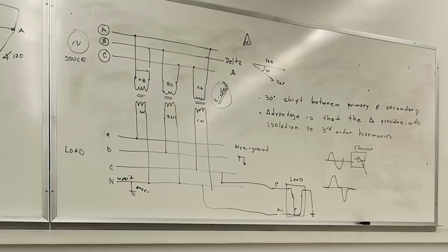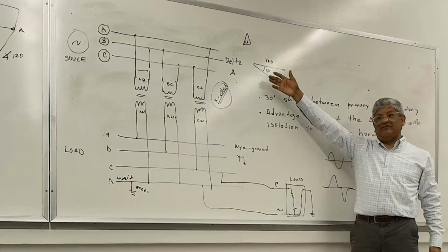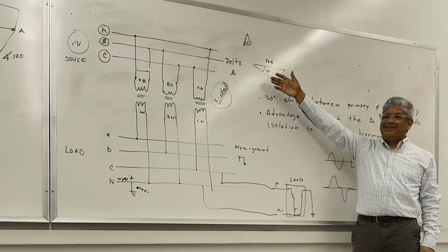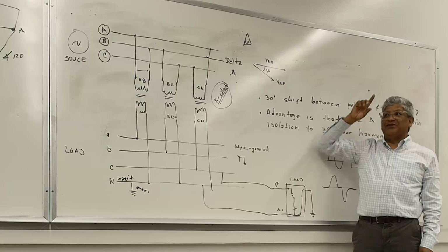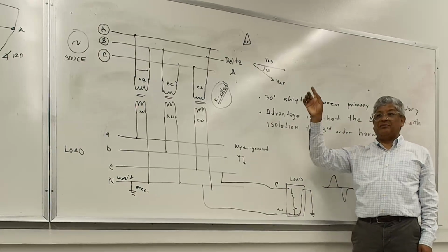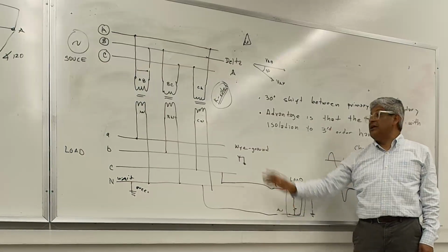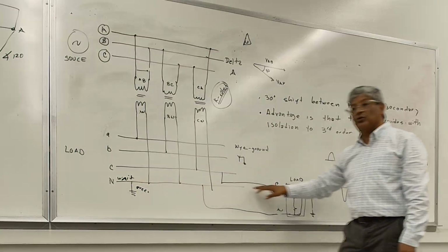house. As I said, remember when I was explaining this, I said it depends. On 500 kV transmission lines, you don't have that. There's no neutral. It doesn't exist. Neutral is earth. That's the path back to the source, and only for fault purposes. So they might have a transformer like this, but they don't actually have a physical wire.